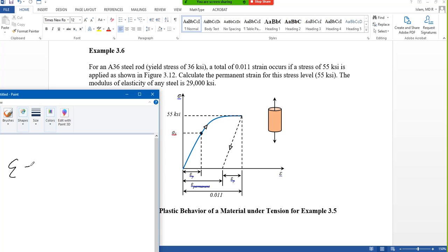Now we saw this equation, Hooke's law. You can remember E is only valid in the elastic region or proportional limit, but proportional limit and elastic limit are not the same. If your problem does not tell you where the proportional limit is, we assume sigma y. I told you in the last class also that this non-linear portion is very small, so most of the time we use the yield point as our proportional limit, although conceptually it is not so accurate. This problem did not tell us the proportional limit, so we will assume the yield point is our proportional limit.